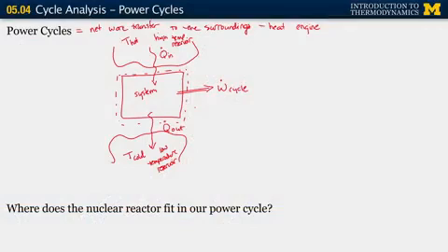Okay. We know that as we move that steam through the turbine, we go from a high energy state to a low energy state. And then we want to close this loop, so we take that low energy vapor and we condense that into a liquid. And in order for us to condense the water, we need to remove heat from that working fluid.